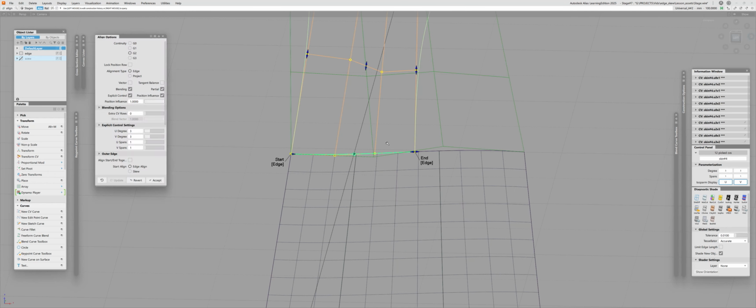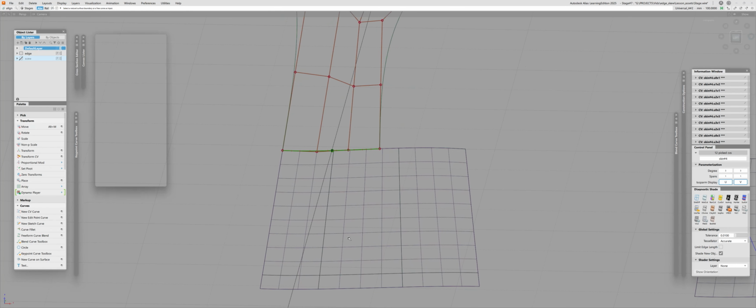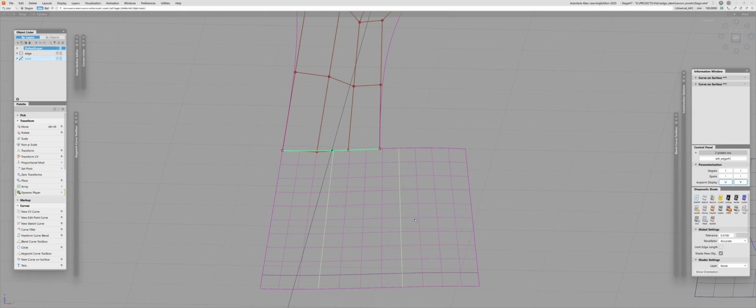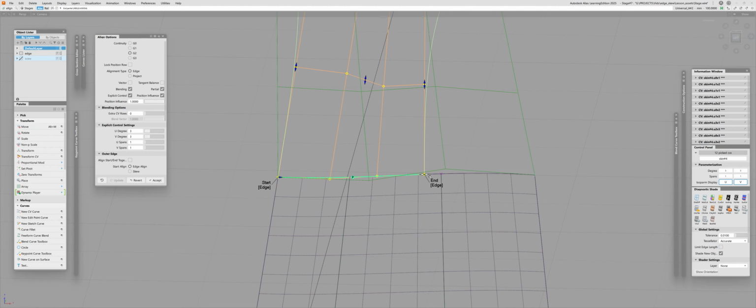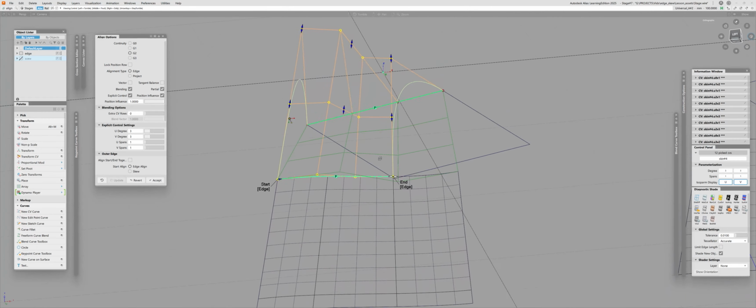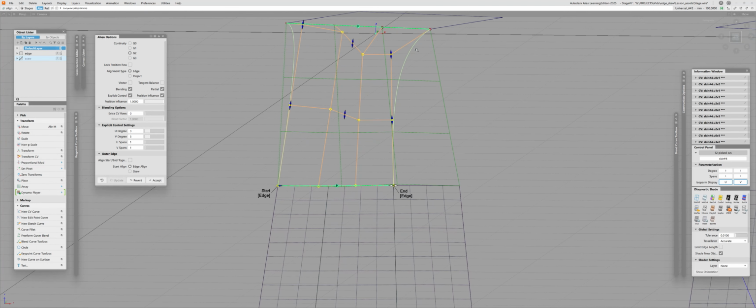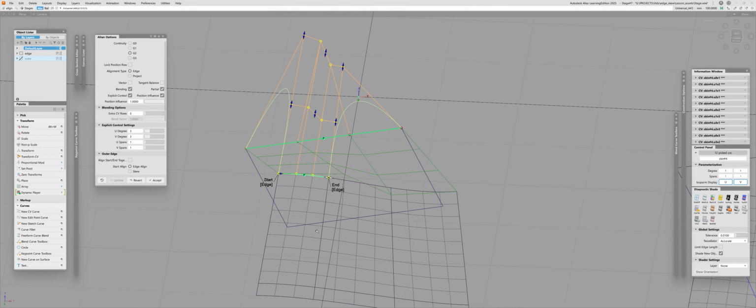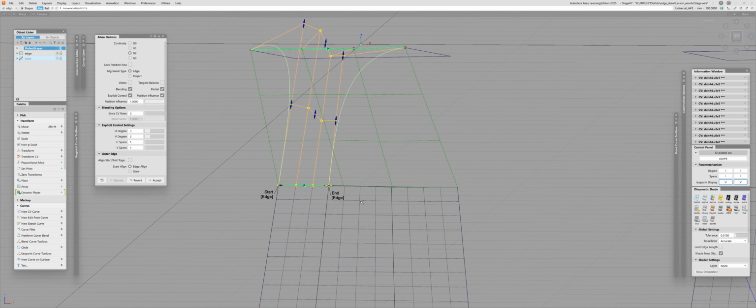them. For example, if I use history, as you can see, I have a couple of curves and surfaces, these and these ones. I basically placed them specifically where the isoparms go, just to illustrate. And if I move that, once again, I'm in the partial alignment, so I will move that and snap it to this point, you're going to see that the collinearity still persists, but it works from the isoparm of the surface. And if I move it here, for example, you can see that now it just aligns to this one. So Alias with the edge align option is not really taking edges, it's taking isoparms. It's taking a domain of points from the surface, from U and V directions.